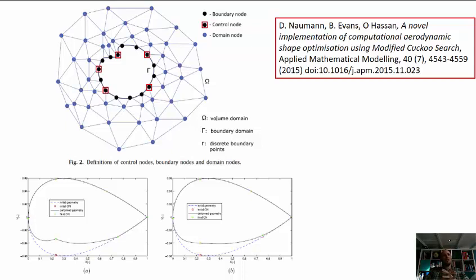One of the shortcomings detailed in that 2015 paper of this method was that, based on the kind of interpolation schemes we were using to move the boundary, we would often introduce, if you had large movements in those control nodes, discontinuities in the gradient, detailed here in the bottom figure, figure A. Discontinuities in the gradient, or kinks as we would refer to them. So in this paper we wanted to develop a scheme where you could smooth out those discontinuities that were introduced by large geometry movements.